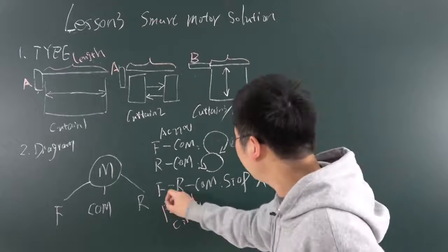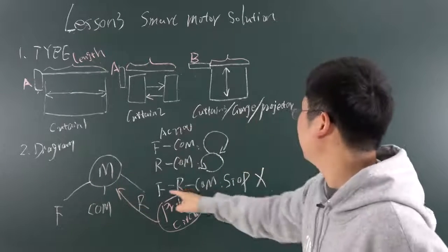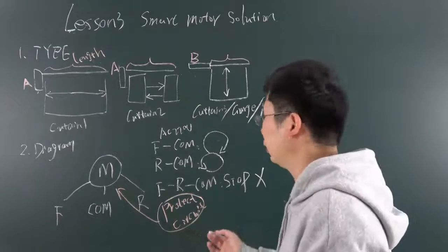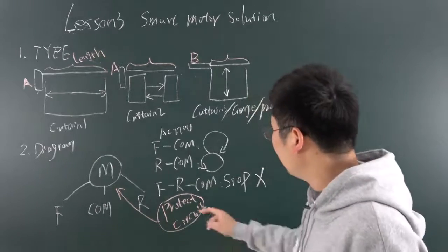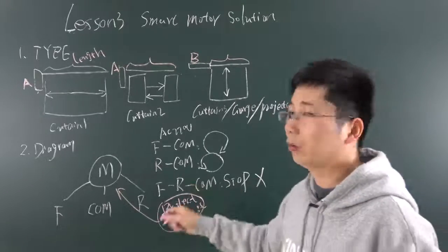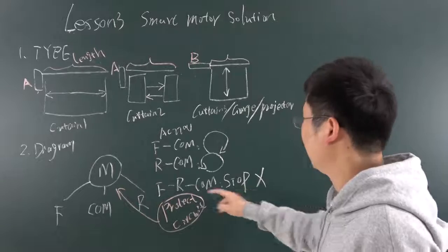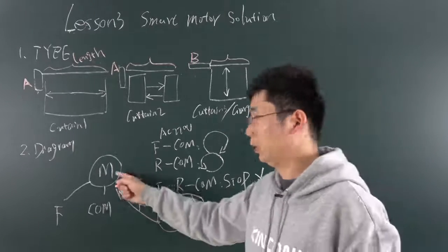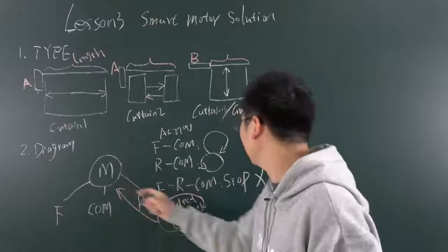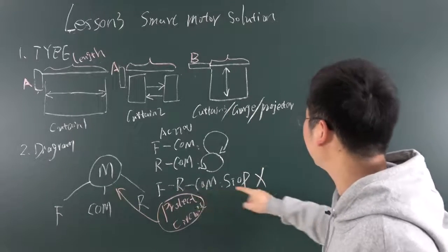If the motor has a protect circuit inside, when you give these 2 points the power, the motor will not be stopped and no problem. But some motors without the protect circuit, maybe the motor will be hot and will become bad, and also it can't run, just stop, but will have some noise and will become hot. So do not do this step. Be careful.